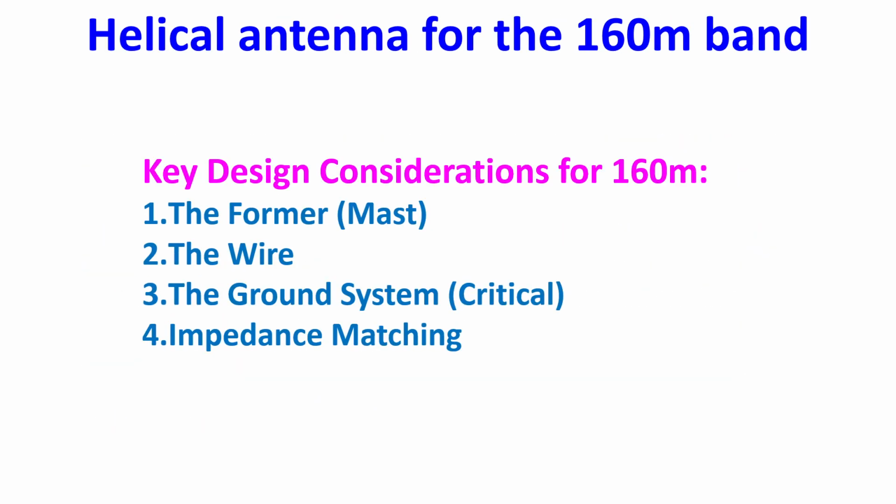Designing a helical antenna for the 160 meter band, the top band from 1.8 to 2 megahertz, that is not in my region but almost globally, means you are building a normal mode helical antenna. A full-sized quarter wave vertical for 160 meter requires a staggering 40 meters, 130 feet, of physical height.